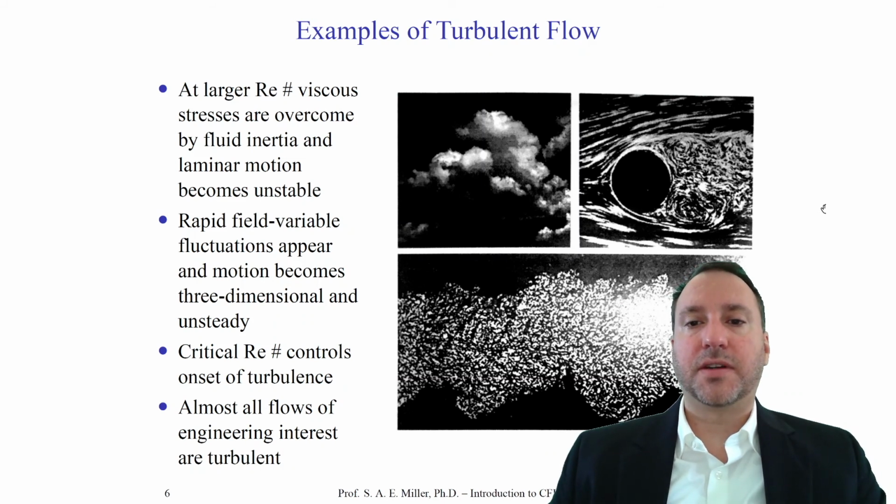The critical Reynolds number is one particular non-dimensional parameter which must be overcome for turbulence to transition in certain types of flows, like, for example, a Couette flow, a channel flow, or a pipe flow. In other types of flows, perhaps temperature-driven flows, there'll be critical Rayleigh numbers. Some of these can be derived completely analytically, and we do this in my Navier-Stokes equations class, which is an elective for graduate students in mathematics, or of course, our field, aerospace engineering.